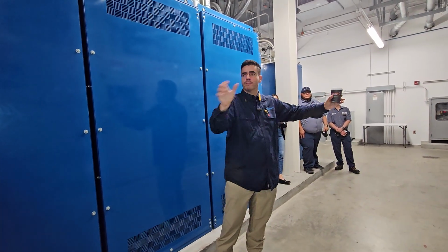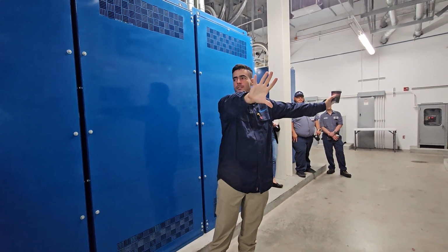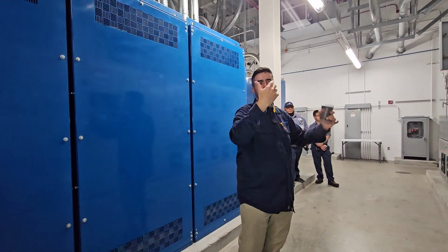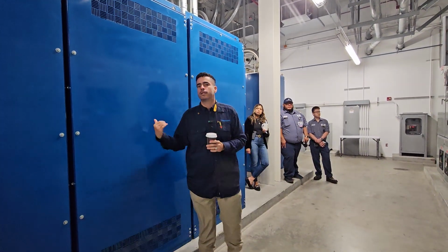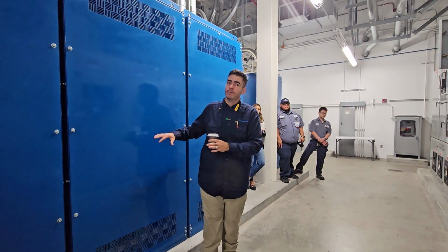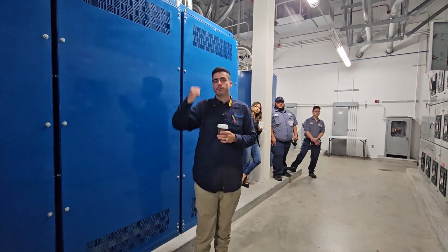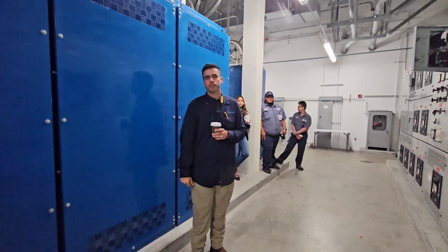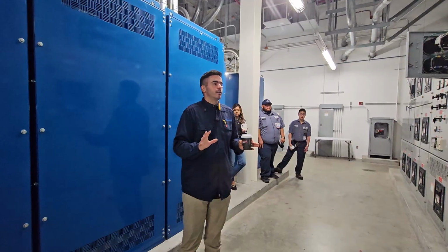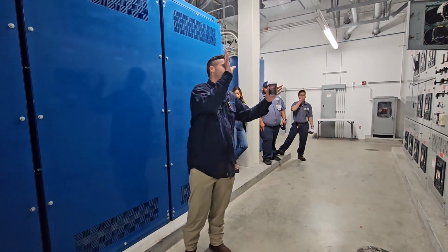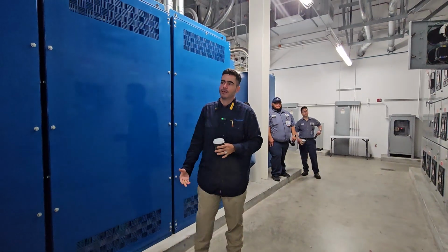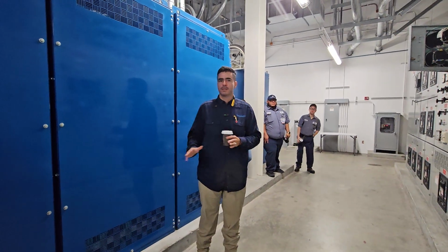So once you come, okay, you lost this, so you come here and you do what Matt did, put both engines online, then go back there. The ATS is going to be already in emergency. But if it has a problem, then you're going to have to do that manual operation at the ATS. But we're going to talk about that in a second. Normal conditions, it will be super unlikely that we have a problem with the PLC and also have a problem with the ATSs. You know what I mean? They are independent. Okay?